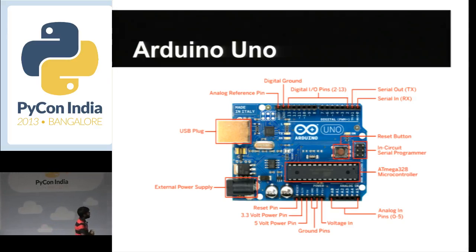Of course, along with the digital pins comes something called PWM, or pulse width modulation, and this is in a way very similar to writing analog values, or something very similar to a DAC. Two of the pins of the digital I/O also pair up as serial TX and serial RX, that is the transmission and reception line of the Arduino, and these are basically the pins that allow you to send data over a serial connection, or RS-232 on a TTL level, and this is how the Arduino communicates with the computer as well.